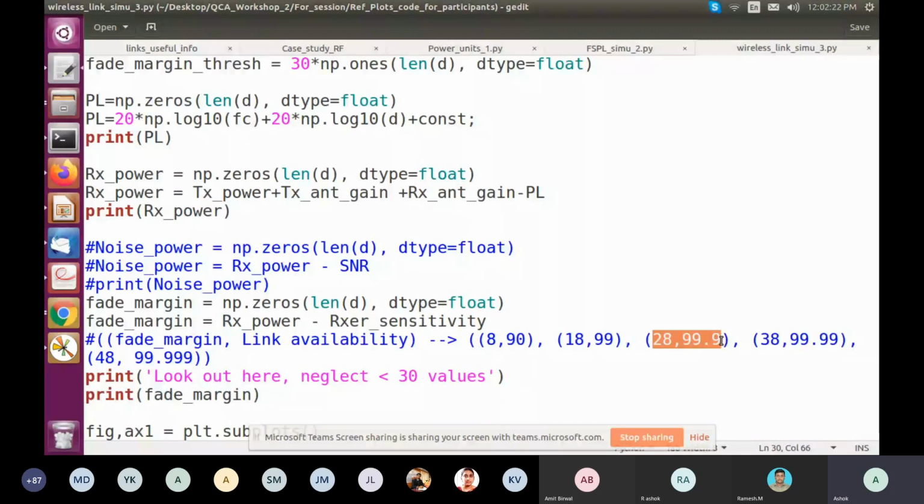But typically for a multipath delay profile, between 25 and 30 dB is considered as your link margin for a typical multipath scenario, where you categorize your RMS delay spread and look at your typical channel characteristics. So for a typical wireless link, you can look at 25 to 30 dB. This will include the fading loss that we have due to multipath propagation. Typically what happens is you model for LOS and then you add a fading margin for multipath.